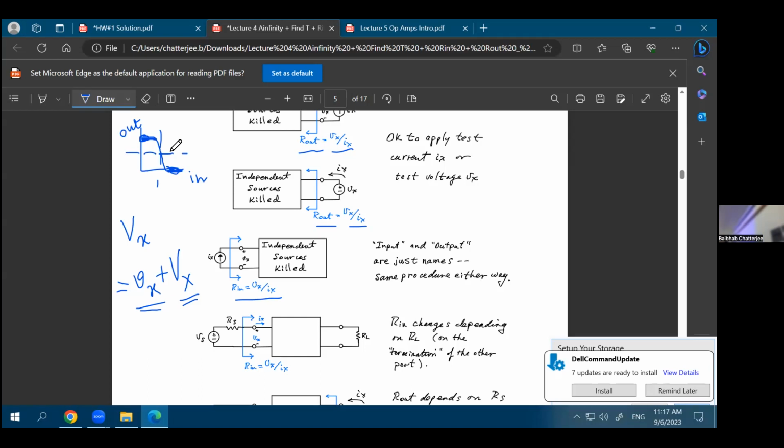So in that case, even around 0 volt, if you apply an AC voltage, you would expect an amplification. But don't expect the same thing if you're applying 0 volt over here. If your input DC potential is 0, and you have a small signal AC on top of it, don't expect this amplification.